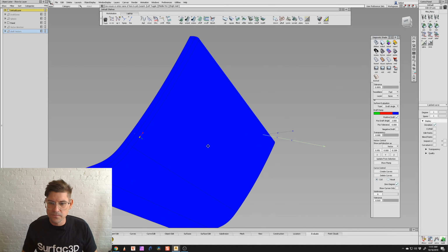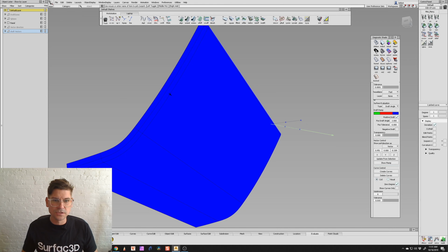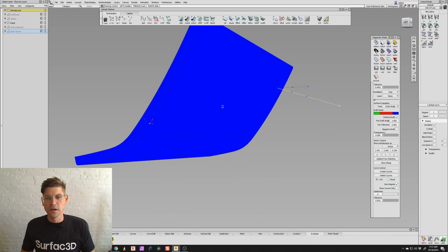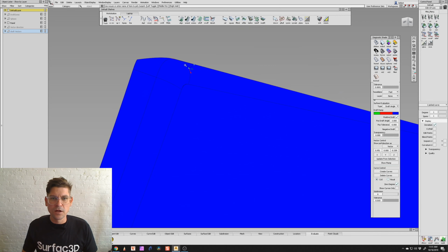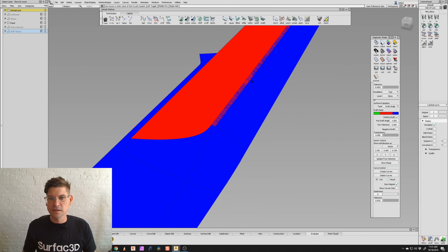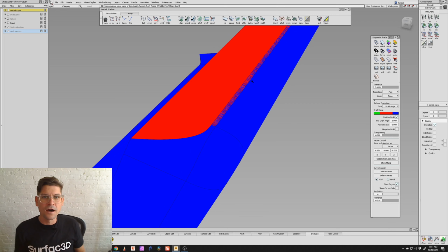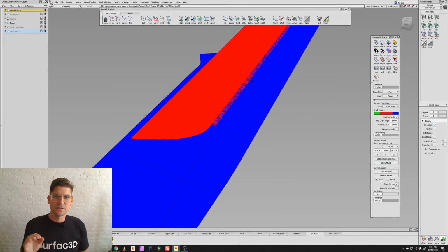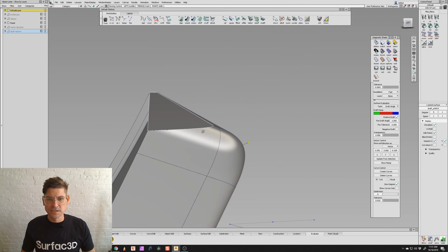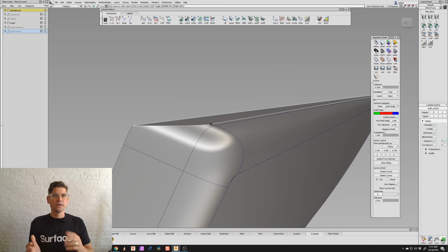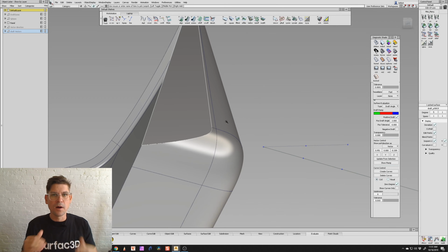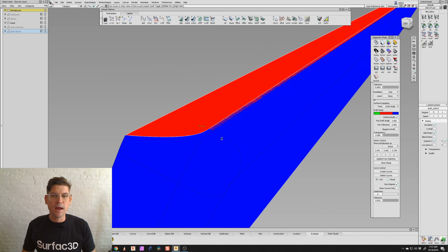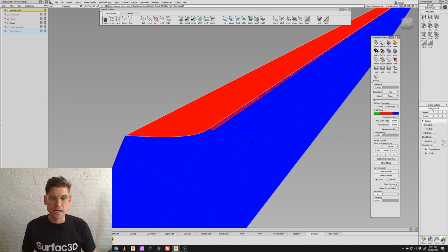And you can see now, from this angle, all of our flanges down here along the bottom side are nice and blue. And then along the top, we have this area, which shows that noise of, it is exactly 3 degrees of draft. It's a flat plane. And then we have this little piece here, which is actually just a flat spot on the top of this panel, which would become our part line. That's where the two parts of our mold will come together. So that part is okay to be red because we want that on the opposite side, the other part of our mold.